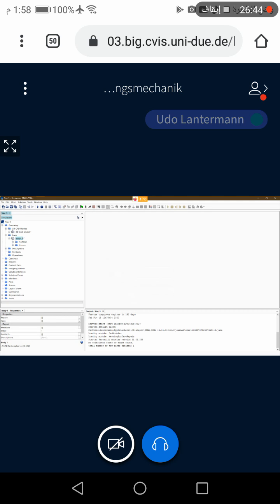Next step is to create the physical modeling, and we have to create our simulation, so our grid for simulation. So at first we will create the physics. Therefore, click with the right mouse button on this continua, new, and then physics continuum.